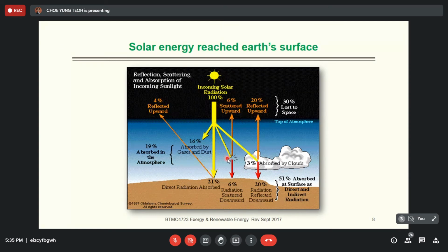So I can say that the sunlight that we receive on the Earth has two categories. One is the direct radiation, coming directly from the sun without any change in direction. Second is the indirect or diffuse radiation, which can come from any other direction. But this is not so concentrated, because all of it comes from different directions. There are 180 degrees that the sunlight can come from, so you will not feel that it's very intense, but the half from direct sunlight is very important.